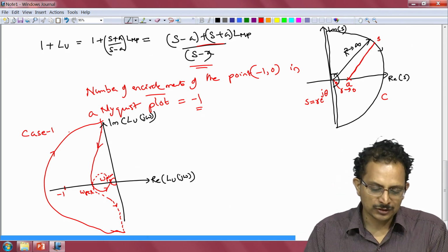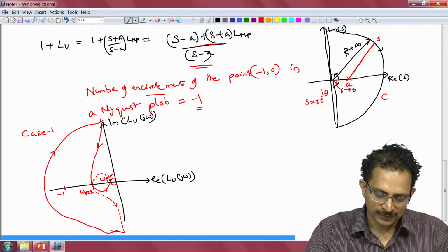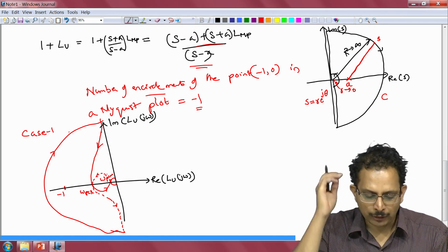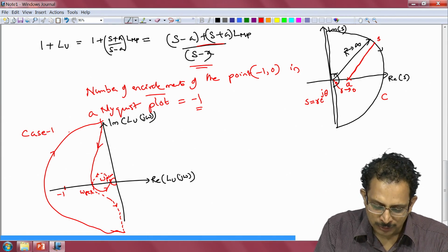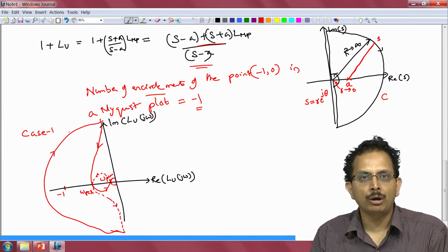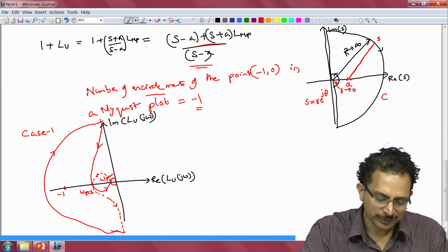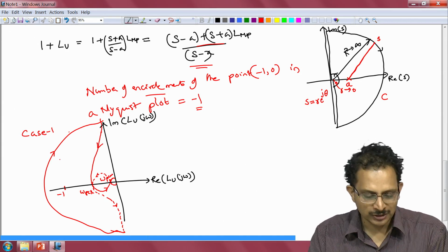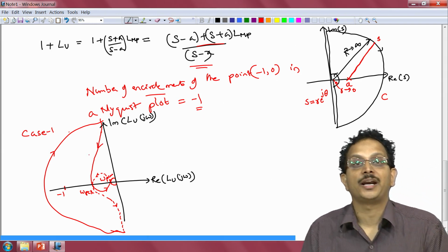Now if we look at this Nyquist plot, we note that the parts that we have to the right of the point -1, the two curves that we have here do not encircle the critical point at all, but this big curve here encircles the point -1 once, but in the clockwise direction.